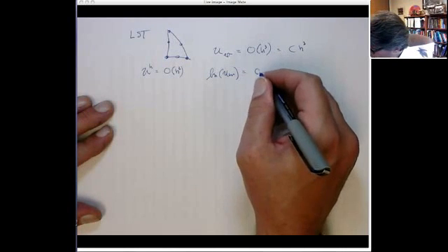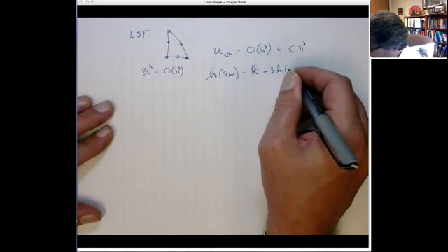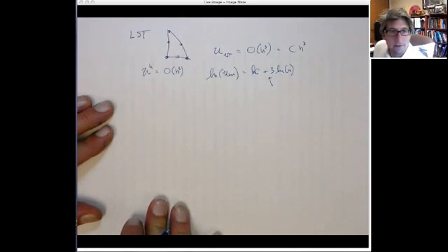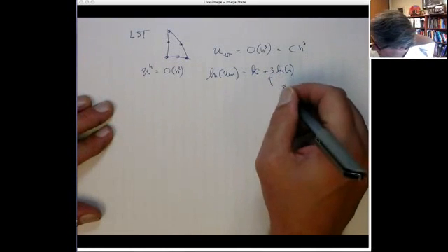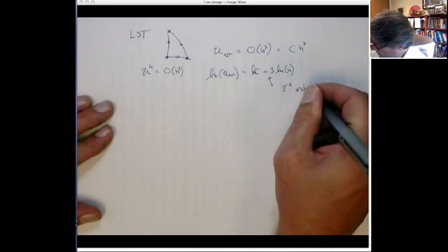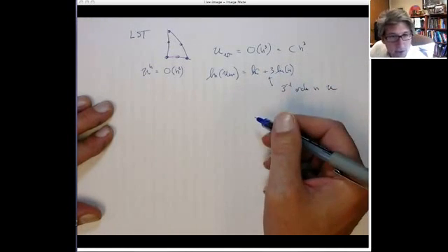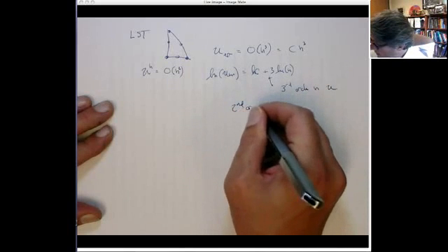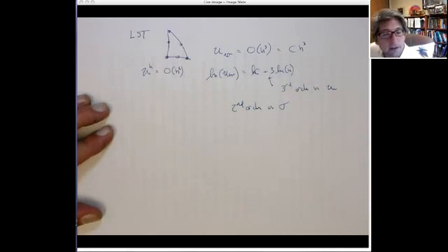So we'll get ln of c plus 3 ln of h. So here's the convergence rate. It's third order, okay? So it's going to exhibit third order convergence. Now, the stress result is going to be one order less than that. So it's going to be second order in stress, okay?